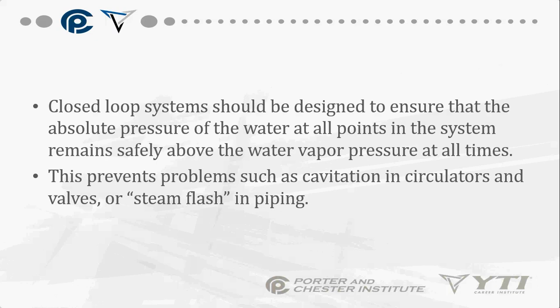One thing here, steam flash. What's steam flash? Just think about the name. A flash of steam. Exactly. If I'm introducing water into a hot boiler that is up to temperature, say 150, 160 degrees, and I'm introducing cold water into that, I'm going to have what is called steam flash. That's where water instantaneously changes from a liquid right to a vapor. That can be catastrophic to a boiler.